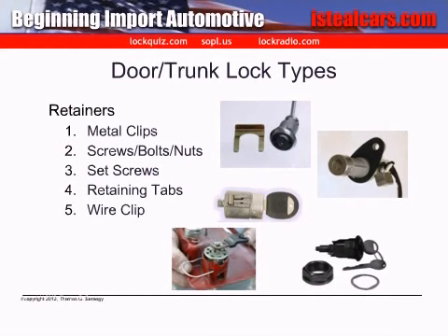Wire clips are probably the most common type of retainer for locks that are mounted to the handle. Finally, used on interior locks, some locks are retained using friction fit components. This retaining method was common on interior gas and trunk release locks for Honda and Acura vehicles.